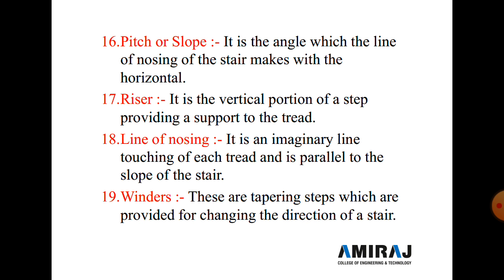Headroom is generally seen on the ground floor to first floor if we provide steps. So here headroom is compulsory, we check. If the headroom vertical height is less, it is difficult for a person to move. Now next is a pitch or slope. It is the angle at which the line of nosing of the stair makes with the horizontal, known as a slope.